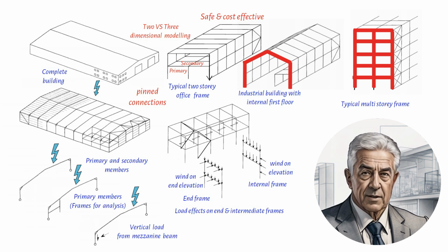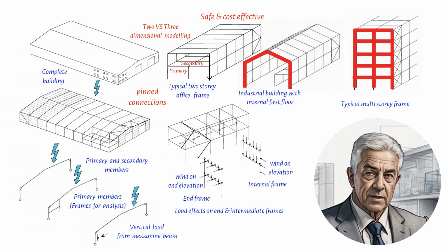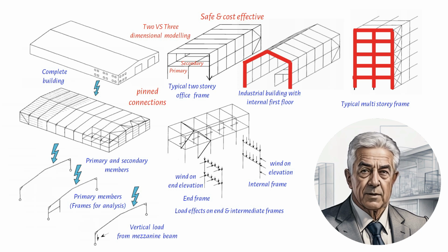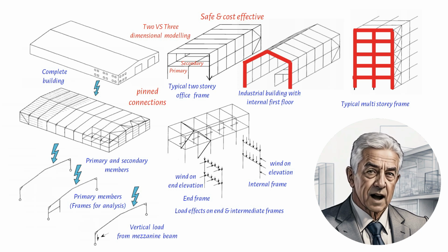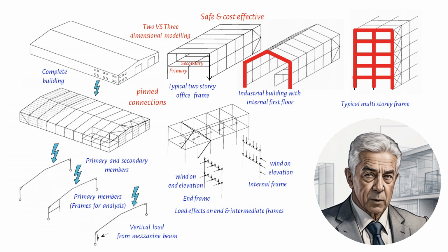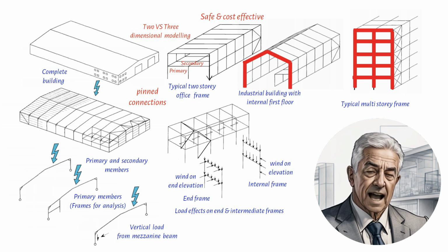Finally, the majority of steelwork structures can be effectively analyzed as two-dimensional models, with the exception of some specialized structures. Two-dimensional modeling is recommended for its simplicity, as well as the ability to replicate frames in real life, which leads to greater economy in analysis, design, and fabrication. Connections to out-of-plane members are typically nominal pins to prevent complex and stiffened connections. Standard profiles are primarily designed to bend about one axis.